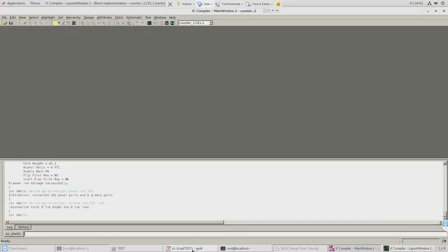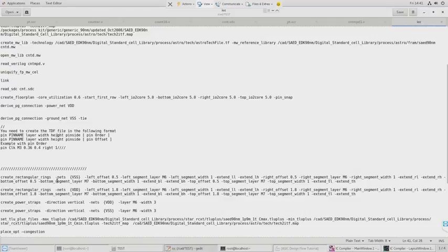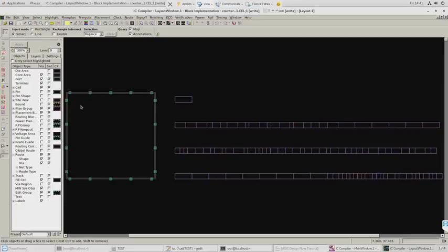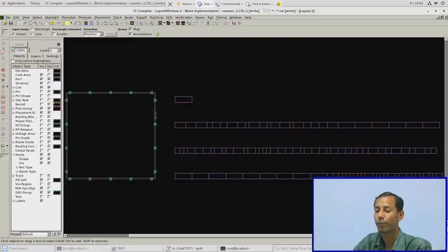After that you can mention the corresponding pad name, but here the tool automatically considers it. Here you see there are in total 18 pins, and 18 pins are already distributed around this floor plan. So 1 2 3 4 5 6 7 8 9 10 11 12 13 14 15 16 17 18: clock, reset and another 16 outputs. So total 18 input output ports are already mentioned here.